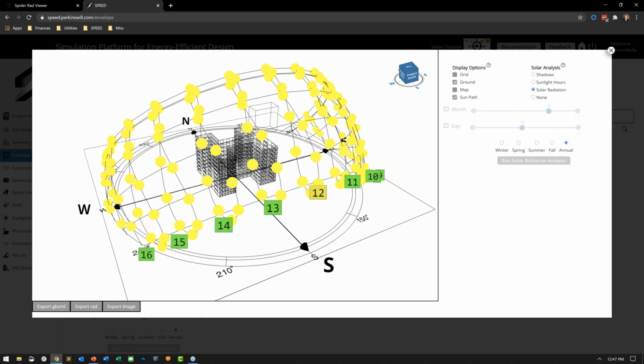But this is basically running on 96 cores. The custom script we have, this is a gbXML file converted to a Radiance file. So we take the native Three.js geometry, convert that to a gbXML file, then to a Radiance file. We pass that to a Dockerized AWS machine that has the script on it. We run it. It generates all the images for the visualizations, returns those images, and that's placed over the Radiance file here in the scene for the user to view, and worked a lot with Teo in developing the prototypes for this.